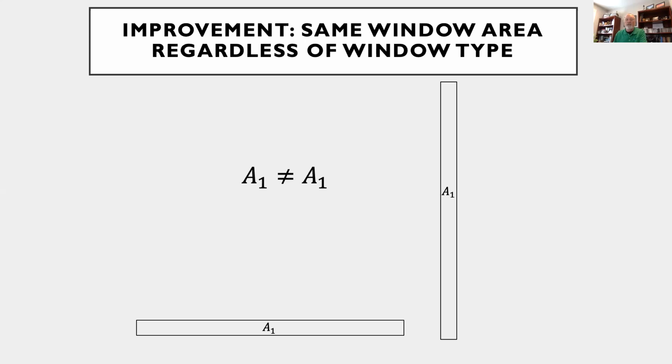One of the big errors was that it just had to do with opening size. Natural ventilation is all driven basically by temperature differentials, right? It's generally cooler outside than inside, and in Europe, where it's perfected, that's the case. So we've got to have this flow: the warm air goes out the top, the cool air comes in the bottom. What's the temperature differential from the top of the room to the bottom? It's higher at the top and lower at the bottom, and you're going to have airflow. If it's all a strip across the bottom, there's really no driving force, and it's not going to work. So the first assumption in the previous standard, that all areas are the same, is a bad assumption because it ignored what the driver was for making natural ventilation work.